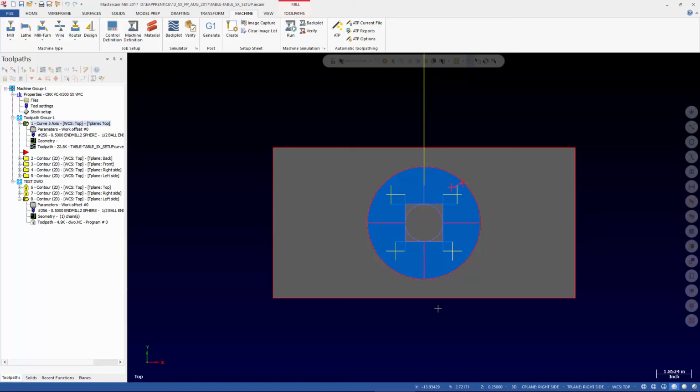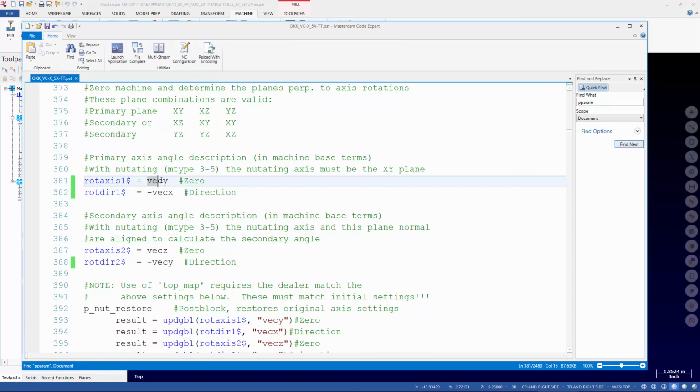And if you're off, change the 0 position. If your rotation direction is reversed, change the sign of the direction. Okay, if you're off for your C 180, it's probably this sign. You've got a negative where you should have a positive, or a positive where you should have a negative.